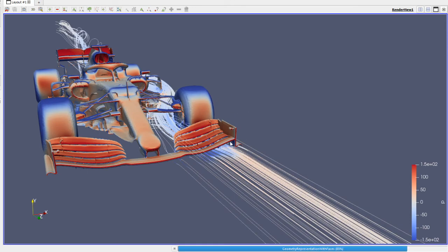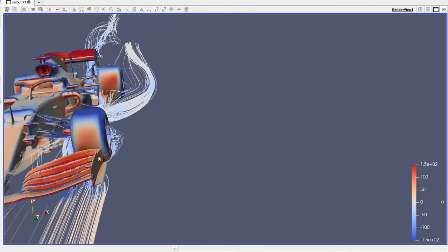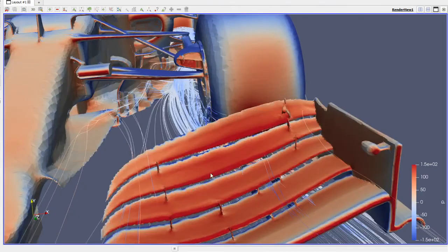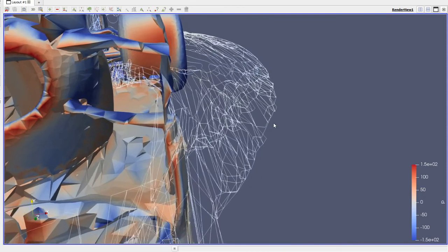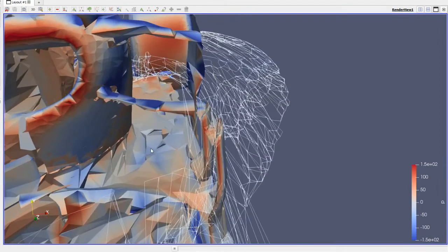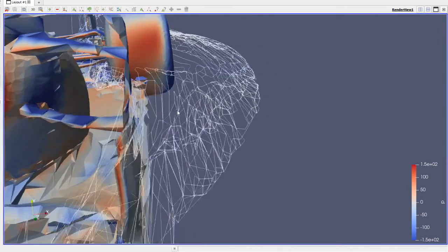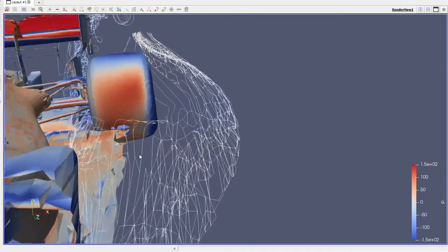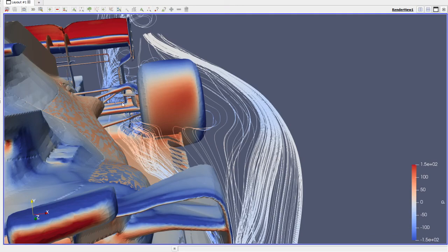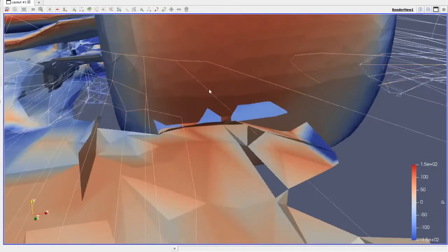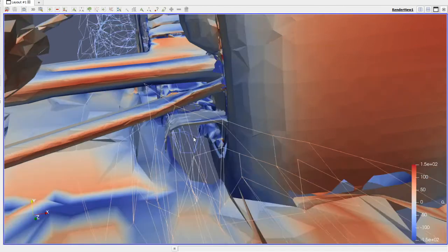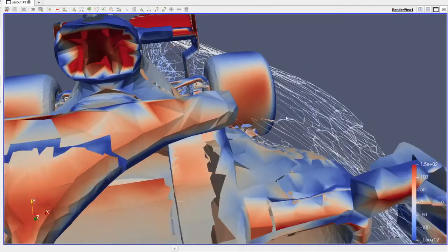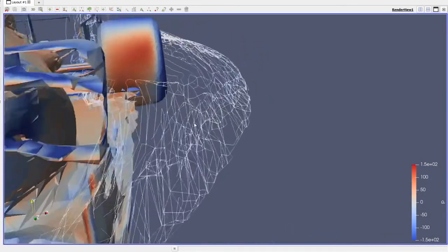So there you can see most of this air from this point is actually the air coming underneath the wing, around the tire, and then getting turned in over the diffuser, and some of it going, so taking this there, turning this back in maybe, to go over the diffuser to try and get some more energy there, through into the brake duct, down the side tires here, over these wings here, try and get more downforce at the back, and also getting pushed out the side to try and seal the car a bit over here.